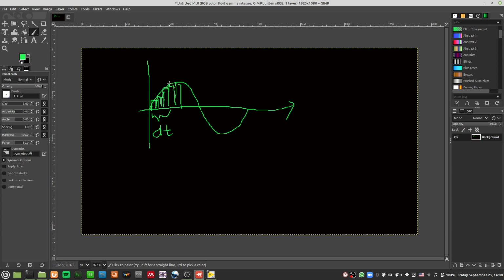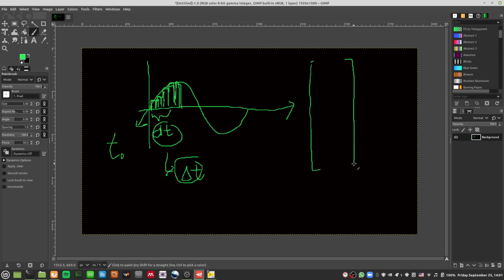Okay, so every time you cross dt, you will take a sample. So in your waveform graph, you will have your dt or delta t. This waveform will actually contain 3 pieces of data: your delta t or dt, and then you also need to know when you start sampling, which is your t0, and then you will also need an array of data, right? Okay, you need an array of data, let's say x0, x1.